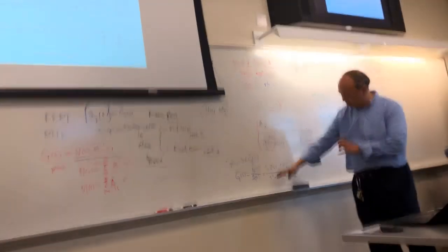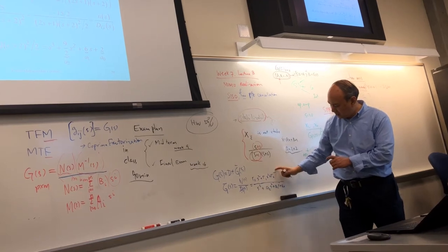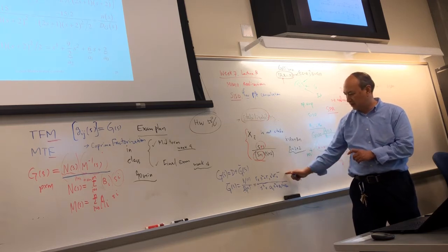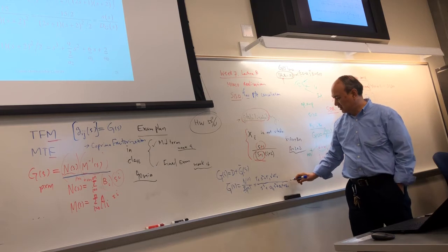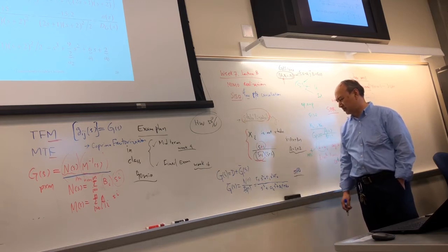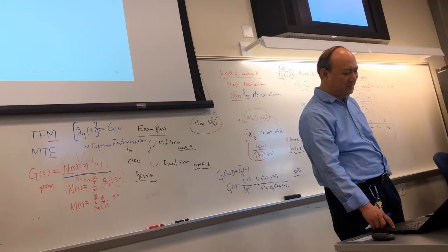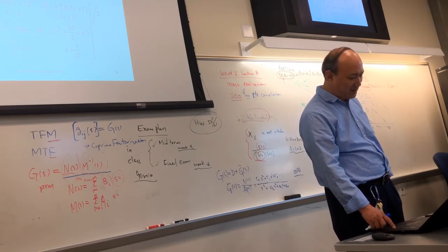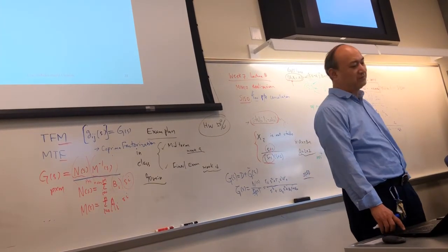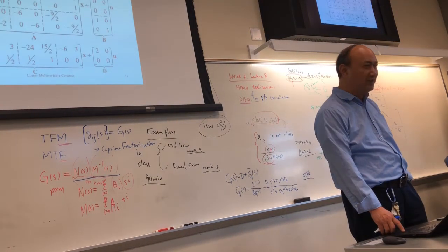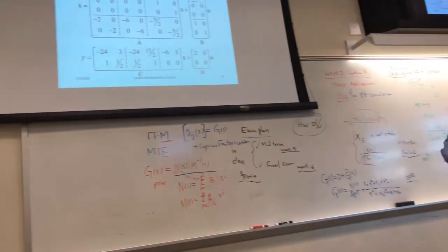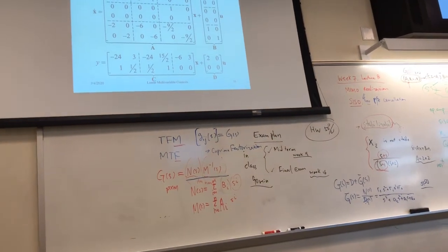So given this is a scalar polynomial, and this is a matrix polynomial, a matrix polynomial transfer function, with that, you use the same SISO controllable or observable canonical form. You will be able to write A, B, C, D immediately in such a way. So you have n of s here with 3 coefficients. So the controllable realization is like this. Basically m is 2, and everything is 0.